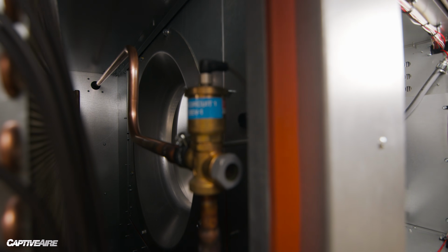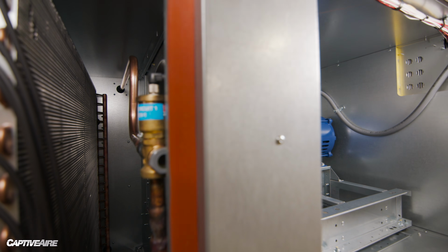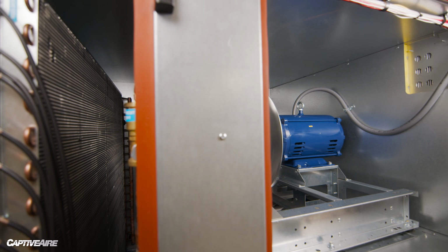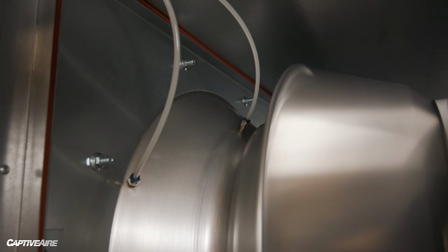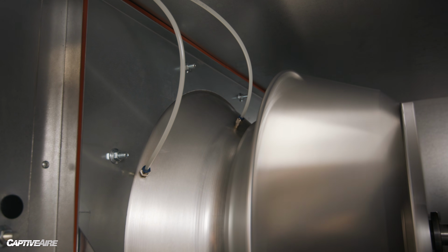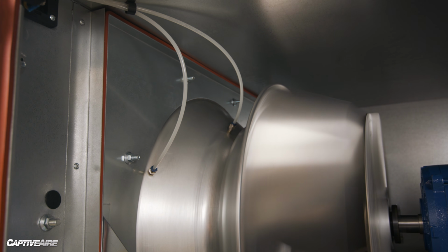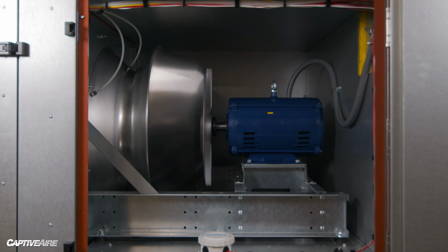We have automated equipment, automated tooling that drills holes in the exact same positions in those inlets every single time. So from those 2 points, we have a pressure drop, and if we have that pressure drop, we can compare it to a theoretical static pressure CFM curve and generate an airflow from that reading. Because we've tested this inlet with our wheel in a chamber, and we know that it's installed the exact same way every single time in our equipment, we know that it's very reliable and very repeatable. So we can tell the user at any given time how much air is coming out of our unit.